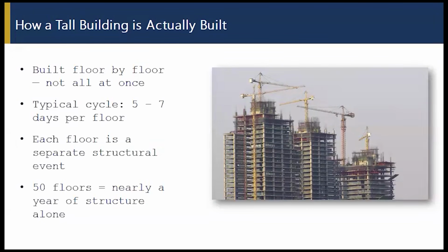Each building is made one floor at a time. They finish one floor, it's like a project, then go to the next floor. Bridge also: one span, second span, substructure, superstructure. So there's a sequence to that. This takes nearly 1 year to make. Over that time, the properties will change, the creep will come in, shrinkage will come in, many things will happen.